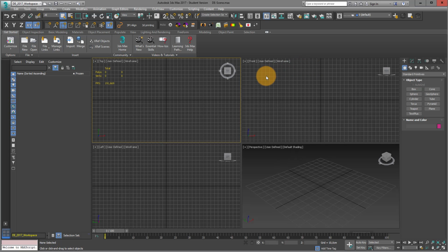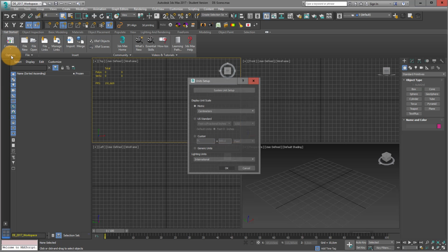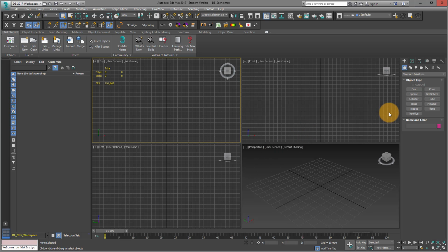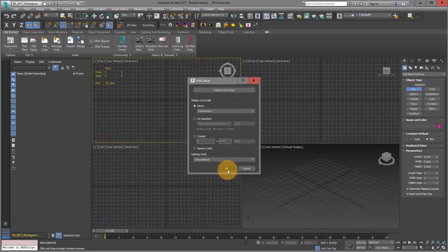If you use the Workspace 3D Studio Max with the design standard settings, and you go to get started, the first thing you should look at under customize are the unit setups. There are display units and there are system units. The display units are the units which are shown in your menu bars. For example, I have the settings like centimeters. I can change it to meters. I can change them to millimeters. Doesn't matter. Really important are the system units.